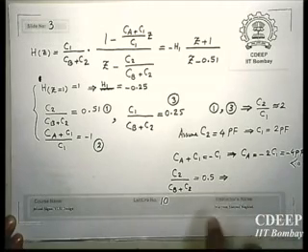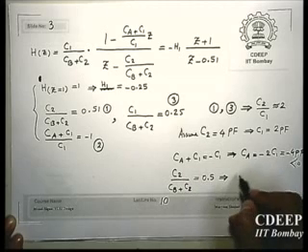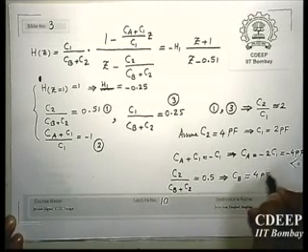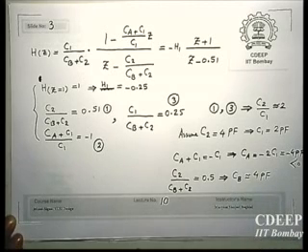Because now you have the value of C2 as 4 picofarad, therefore CB will be almost 4 picofarad as well. So now you know all values, right? Therefore, we have designed a first order switched-cap filter with the characteristics which were given in the example. Now, how to implement a negative capacitor?